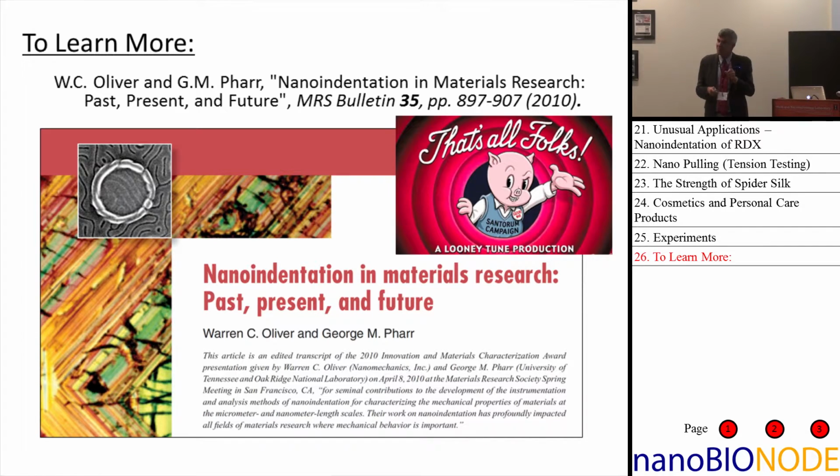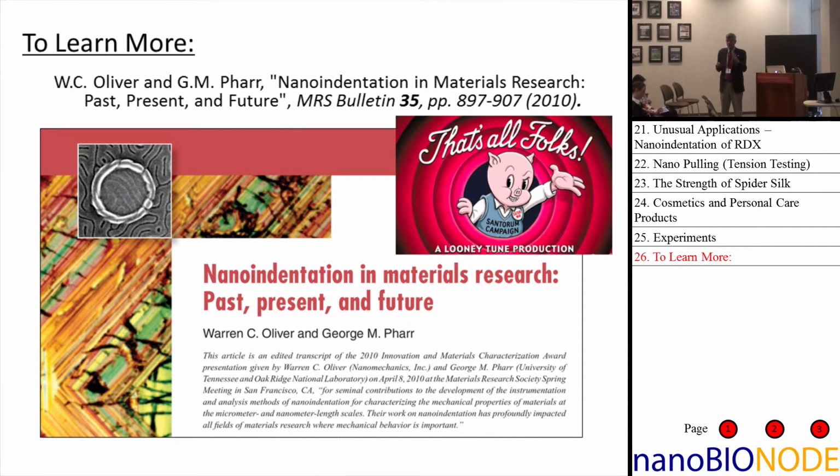But it turns out that in certain materials, that's not a good assumption anymore. Since that was discovered about 5 years or so ago, the software in all of the machines that we use has been changed so that it is the load plus the amplitude that is used as the magnitude of the local peak load.